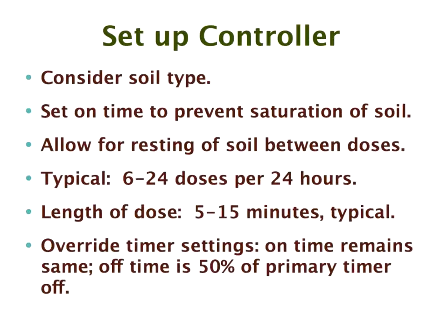That 2 hours in the case of a good alluvial soil, you might run for 15 minutes at a time, which means you run 8 times a day, once every 3 hours. On a very heavy soil, you might bring it down to half the time, say 7 minutes, 7.5 minutes to make it easy, and run 16 times through the day, which is, I think, every 1.5 hours.